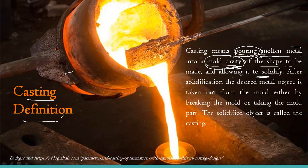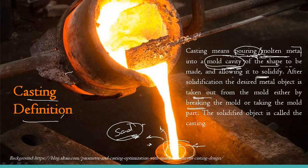After that, we can take it out of the mold cavity. There are two ways. Generally we make this mold from sand, so we can break the mold. If it is made of some other material, then we can simply shake it in this direction and remove the material. Whatever solidified material has been removed from this mold cavity, we call a casting. So this is a simple definition, and that solidified object is called a casting.